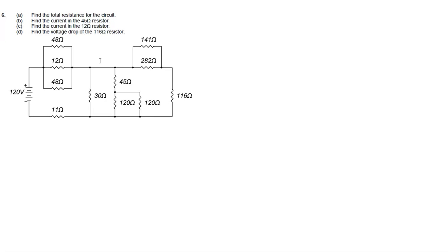You'll notice that when Mr. Chalk did the drawings or the redraws of it, he didn't bother to label the resistors with R1, R2, and so on, but he did label the junctions. And he's really big on putting a little black dot on each of the junctions, right? Where we would consider it to be a node. Now a junction, like this one down here, is not really a node because current doesn't divide there. Anywhere where current divides or recombines, he puts a black dot on, and he's really big about that.